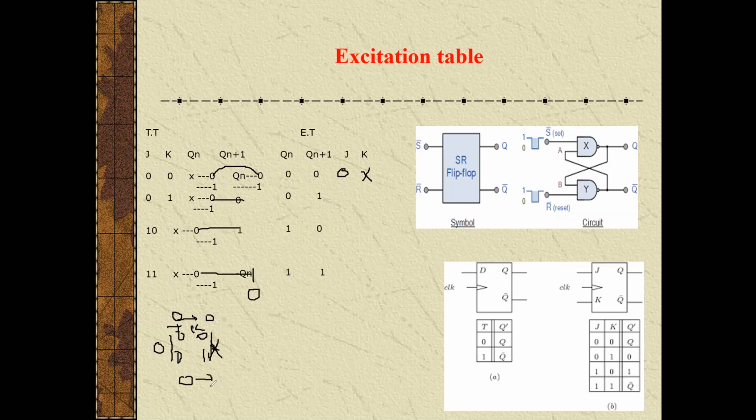At what stage of the input will this 0 to high combination occur? First one is 0 to high when J is 1, K is 0. And second combination is both are 1, 1. J is 1 and K is also 1. So here J is high in both conditions, K is toggling. So the possible combination is 1 and this is undetermined. So let's see the next state.